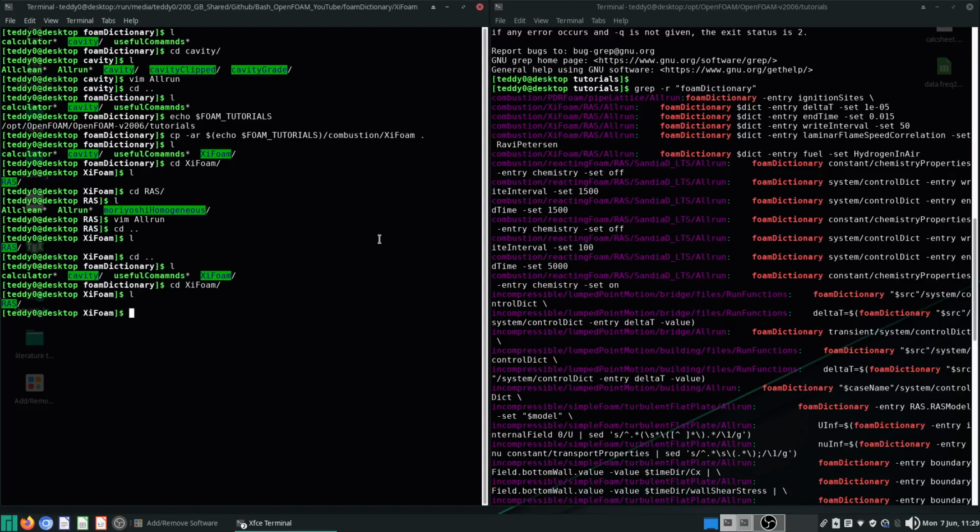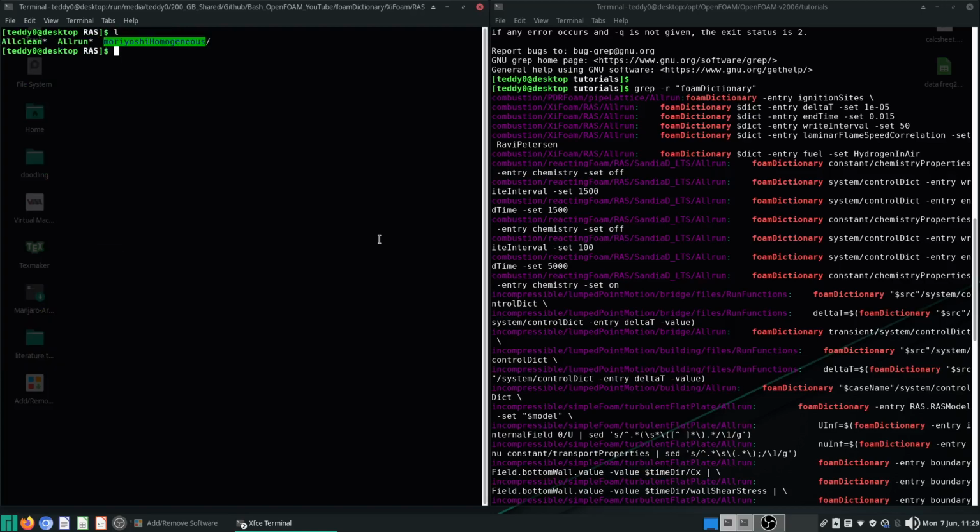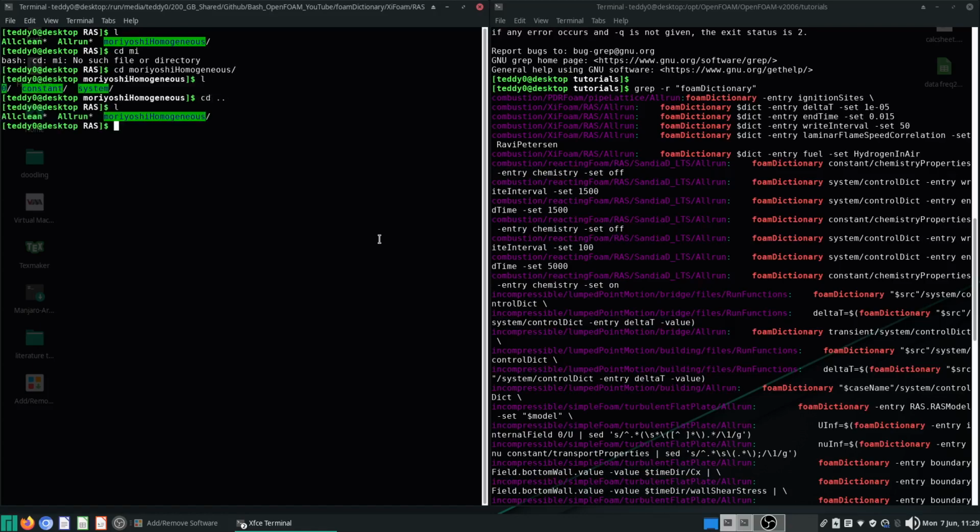Let's look at the foam file again. We only have one entry here, the RAS entry, and there's something called the RASProperties homogeneous. But you notice the Allrun file is located outside the case, because this is where your OpenFOAM case is: 0, constant and system.